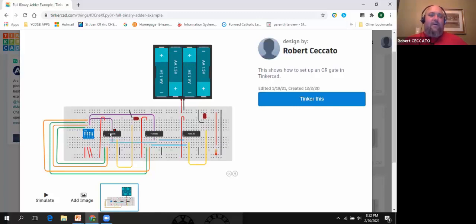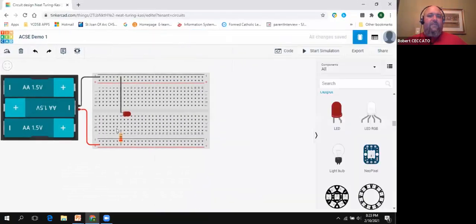normally for those of you that know how ICs work, you've got to give them 5 volts directly, and you would use the voltage regulator to do that. I tried to use the voltage regulator. I found it was quirky. So the best thing was to literally set up 4 AA batteries, and I put a 220 ohm resistor, which dropped just enough voltage to make these suckers work perfectly. But that's neither here nor there. If you want to go into that a little bit more, then definitely that's something we can look at in the future. But I'll tell you, for building stuff with students, very, very simple, very fast.